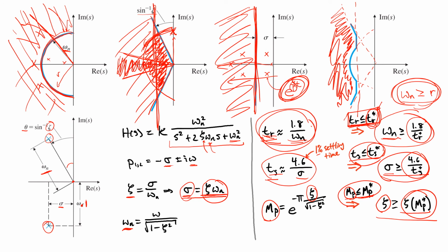So this geometric interpretation is particularly useful when you have the potential of designing different controllers and possibly even different system dynamics in order to figure out what will work. And so one of the main tools that we will use is the overlapping of this geometric interpretation with our knowledge of the root locus.